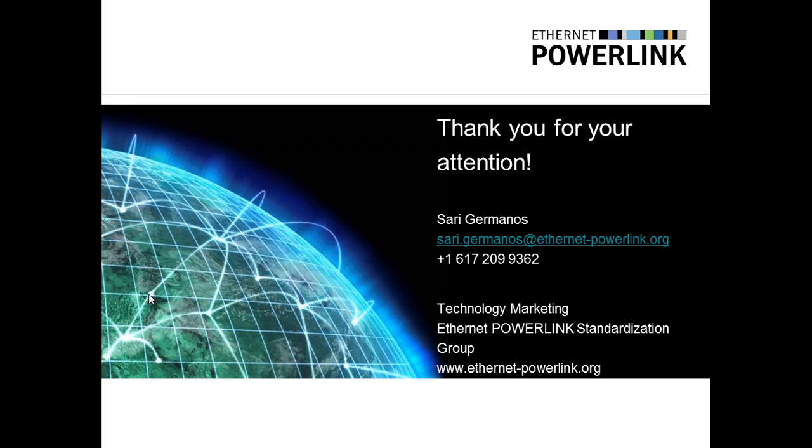So anything that you can do with EtherCAT, you can pretty much do with PowerLink. As I showed earlier, there are some cases where if you're in a noisy environment, PowerLink is going to be a much better standard because it is more immune to noise. If you need to do slave-to-slave communication, as I showed you, it's also better to use PowerLink because in EtherCAT, the packet has to go to the master, then back to the other components that need it. Whereas in POWERLINK, that communication happens directly, so you can do time synchronization much simpler.